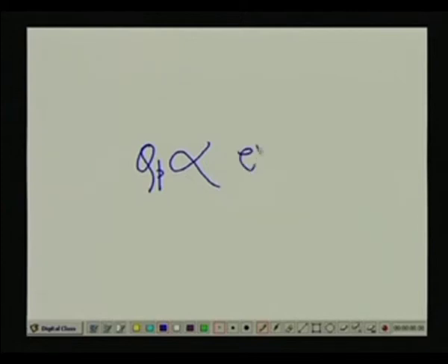That means in all the single amplifier structures, positive feedback as well as the simple negative feedback topology, Sallen-Key, low pass, high pass, band pass, as well as the multiple feedback circuits or negative feedback circuits without any positive feedback, you will find that QP is directly proportional to the element spread.